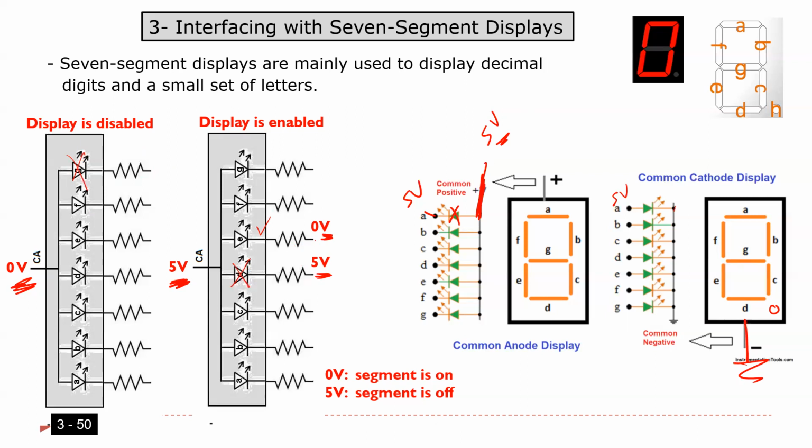The conclusion is that the 7 segment we have here, it's even written up here, it's common anode. So how can we use it? Number one, the common anode has to be connected to 5 volt. You don't need to do that because it is done by the board. The board is going to connect the anode internally, so the anode is connected to 5 volt here.